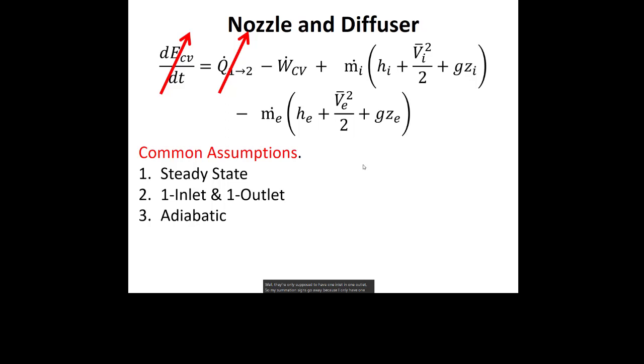I wouldn't advise you to put your hand on the nozzle at the back of a turbojet engine when it's operating. But it's probably hotter than the ambient temperature, so there is probably some heat loss coming off that nozzle. But we're going to say that that heat transfer term is pretty small compared to the changes in enthalpy and the changes in kinetic energy, because remember, that's the main transaction happening in these components.